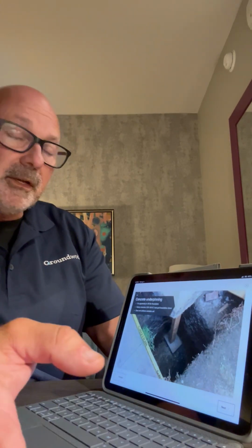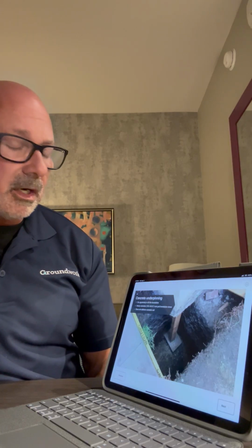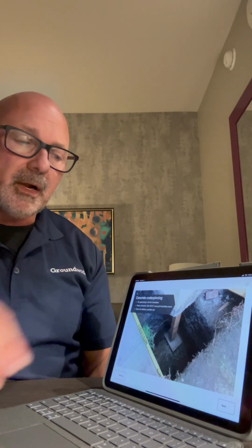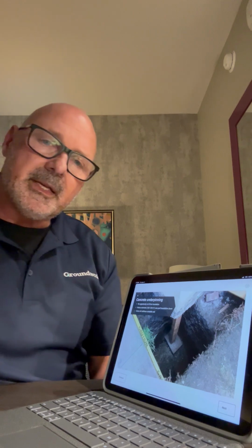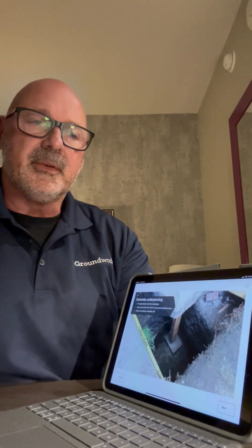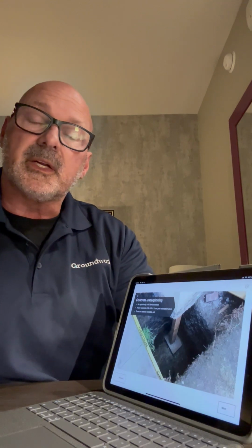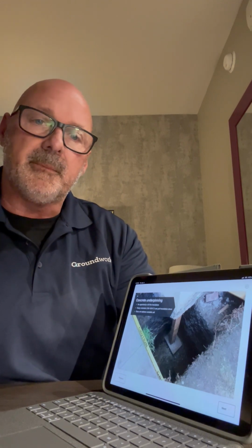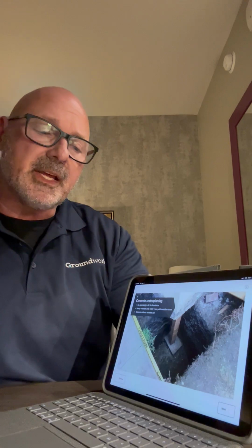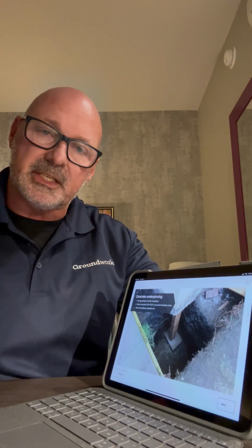And so another thing that people have tried in the past is concrete underpinning. You see that we dig out around the foundation. The idea is, like a lot of people say, do you walk in snow with your regular shoes or snowshoes, right? If you're walking in regular shoes, you'll sink into the snow. It's easier walking in snowshoes because there's more surface area to keep you up. And so that's the idea, that people thought maybe if the footing was wider, then there would be more support, less of a chance of it sinking into the earth.